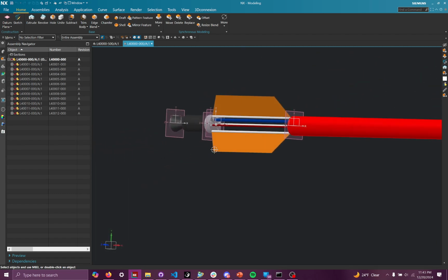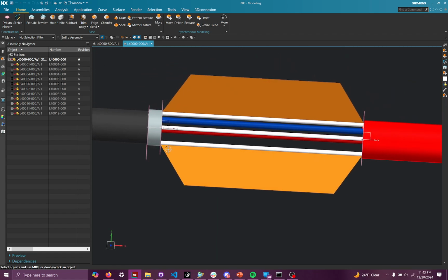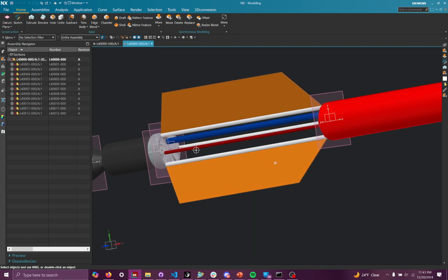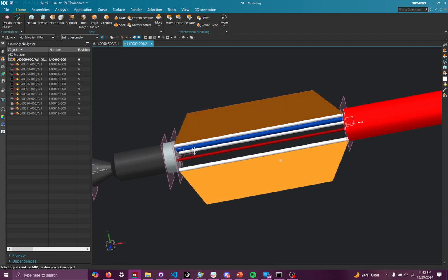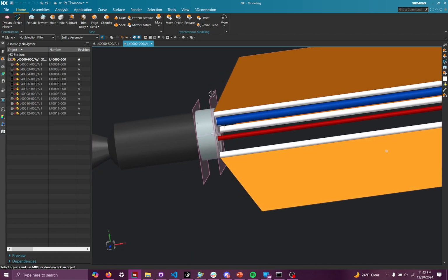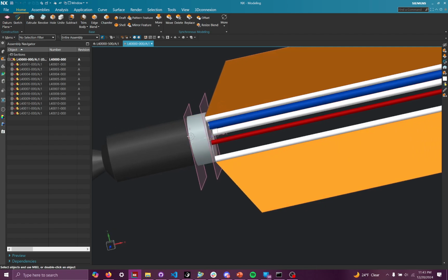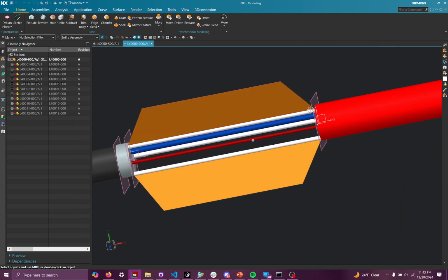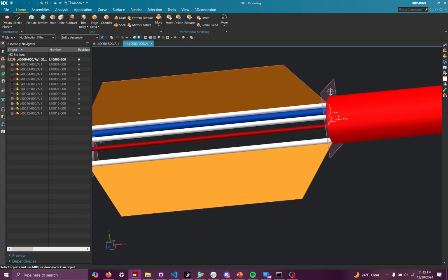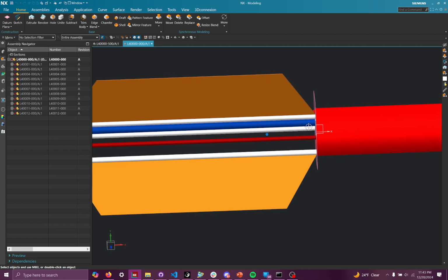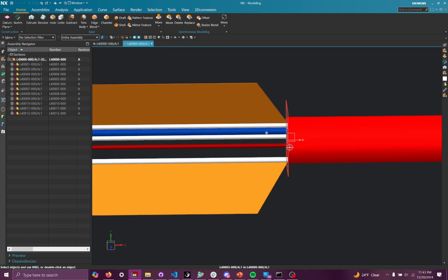So if I'm looking at lower airframe right now, which is comprised of 3 struts, 3 fins, and that's pretty much it, the lower boundary is set by this datum here, which is purposely put right on the top of this injector body. And then the upper bound for the lower airframe is at the boundary or interface between the struts and the fuel tank.